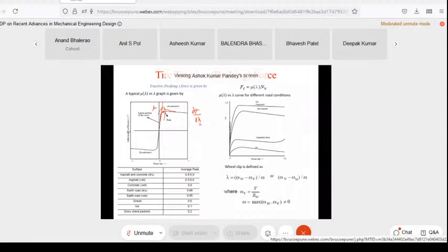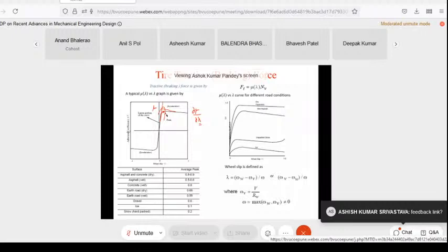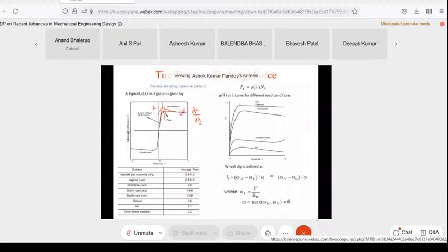But the important thing is that this curve is very peculiar for the tire and wheel interface, right? And here you see that this peak value reduces based on the type of the road. Here it is dry road, here wet road, unpacked one, the ice road. So that's why you see that we can't really increase the speed of our vehicle when the road conditions are different. So for ice, a tire cannot afford to go beyond this. Okay, so hence the speed limit is also there.